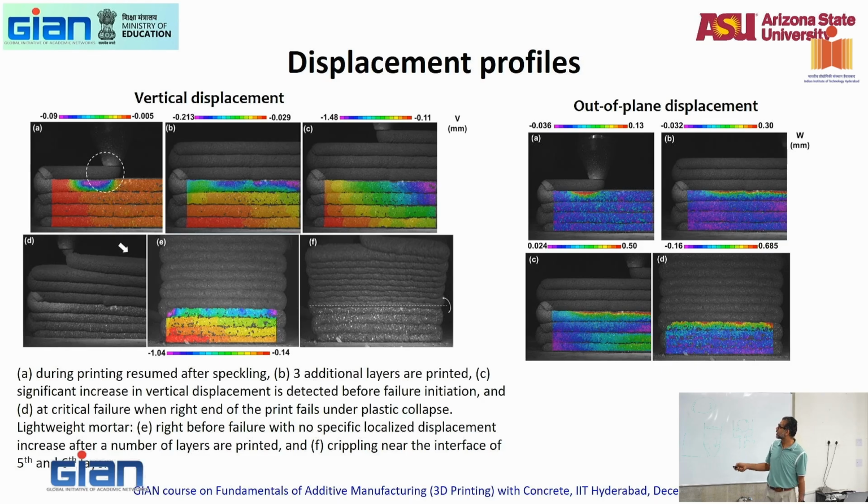You can see here all of that vertical displacement. You can also measure the out of plane displacement. Why is out of plane displacement important for me? Buckling, right? Buckling is out of plane. So now I can find the out of plane strains. If it's going to be buckling, that's dominant. I can look at vertical displacement to see if yielding is dominant. I can look at out of plane displacements and strains to see if buckling is dominant.